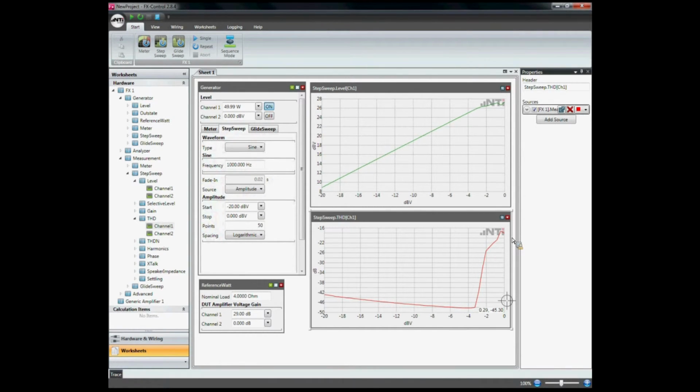Now, by knowing this information, we could change our test parameters. We could say we want to execute this linearity test, but not with an output voltage, but to make sure that the amplifier output has a certain power, a certain watt. Let's say we want to sweep from 1 watt to 120. So this is actually the same principle that we did before. We enforce a certain output power of our amplifier. Now let's repeat the step sweep.